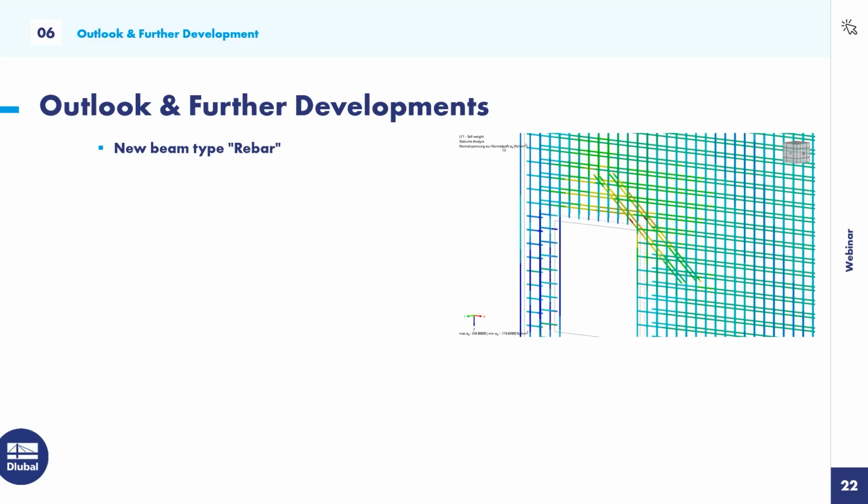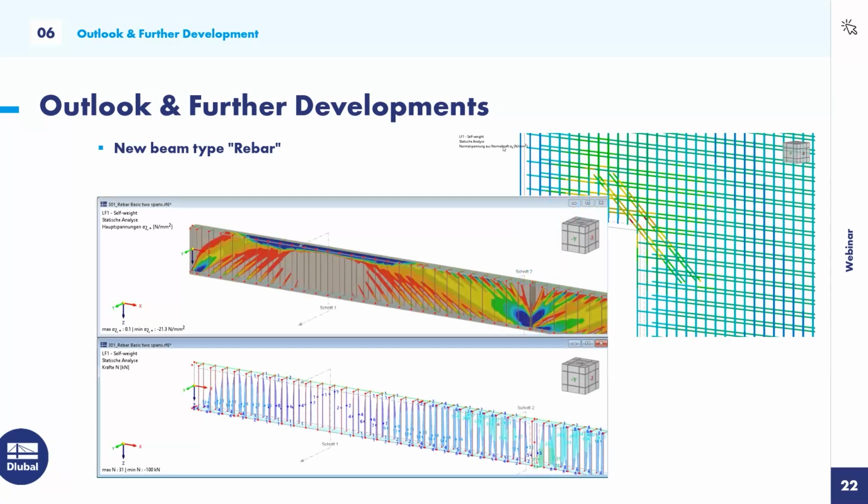If you work together with the nonlinear material behavior, with the damage elements, then the concrete is considered cracked, and the reinforcement will take all the tension strains, and you can also design, for example, deep beams or some walls like here. What is possible? We made some tests here, more as information, to show what is possible and how it works.